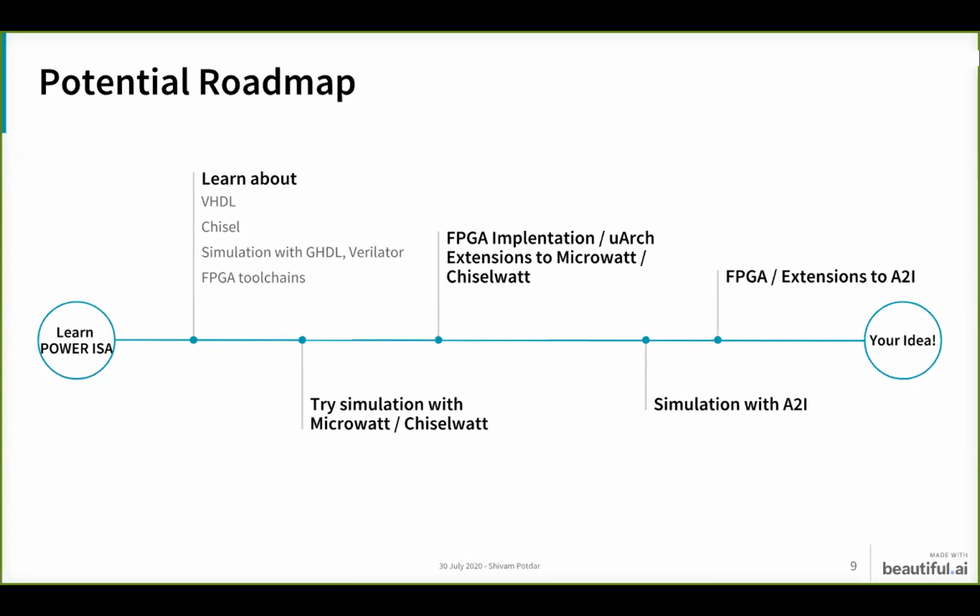Yeah, I'll address one question which is there in the chat, and I'll come back to this. Someone has asked, what is a soft core? So one part about building a CPU is just the hardware description, which you would write in, say, something like Verilog. That is just a hardware description, which you can then synthesize into a netlist, like basically the actual hardware structure in terms of gates or something, and then you can make an actual silicon chip.